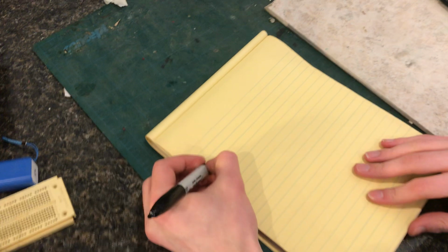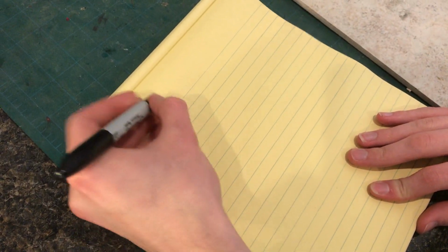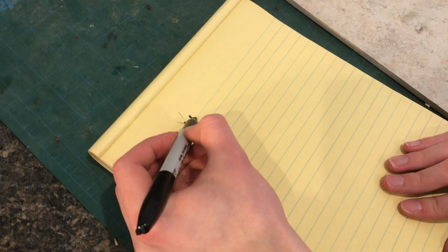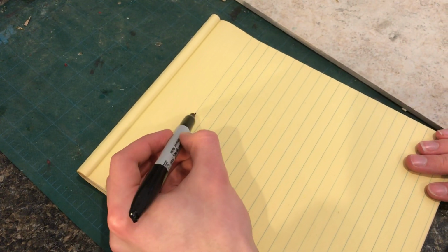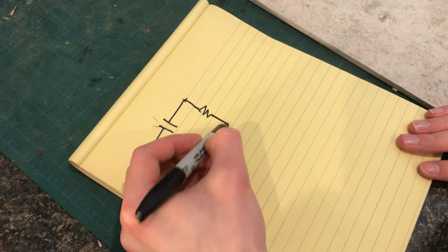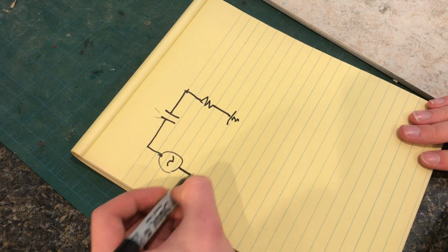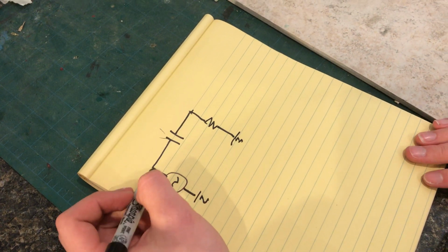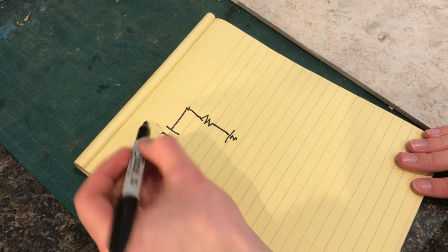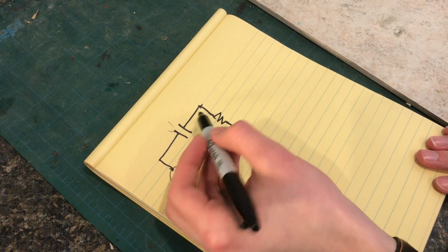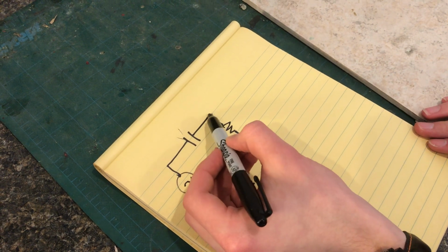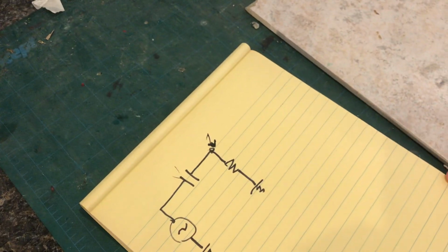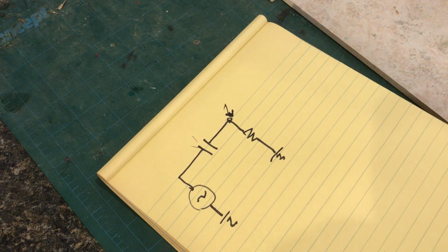So just real quick, I'm going to do high pass, which behaves intuitively the opposite. On a high pass, instead, the capacitor is in series with the power supply, and the resistor is what goes to ground. Exactly the opposite. High frequencies will pass easily through the cap, and at low frequencies, the capacitor will block, of course, and we take the output voltage. Here, the math is the same.